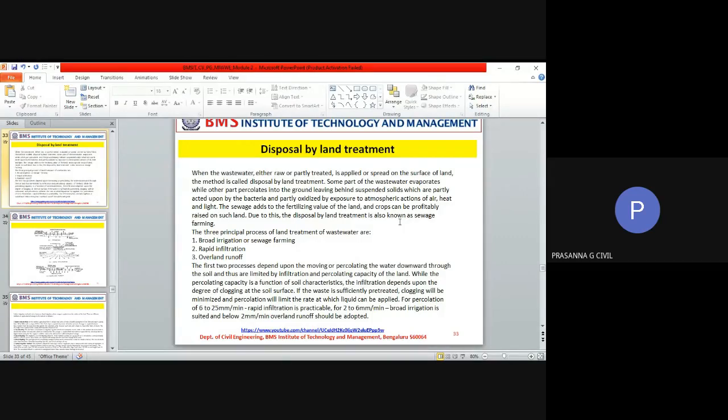The thing is, we are actually not expected to put untreated sewage into water bodies, and we have a regulation. There is a standard Central Pollution Control Board regulation that the BOD has to be brought down to a certain level before you are allowed to put it on water or on land. So we are never supposed to discharge sewage into water bodies directly.